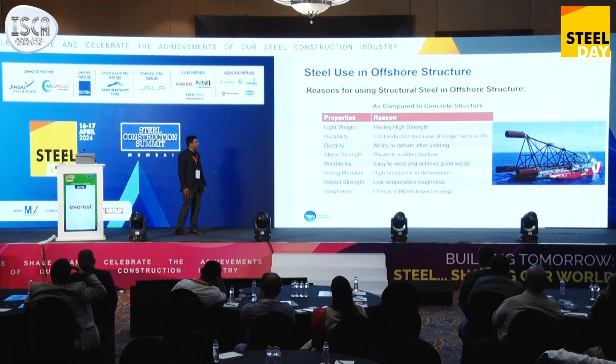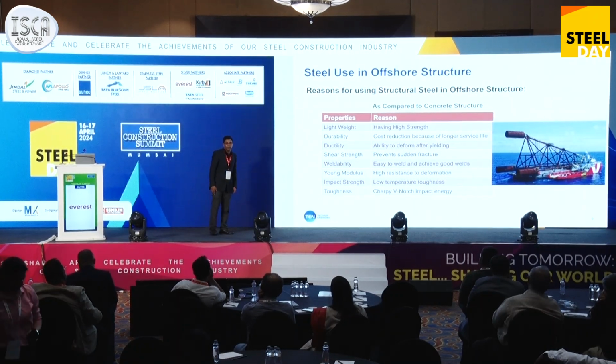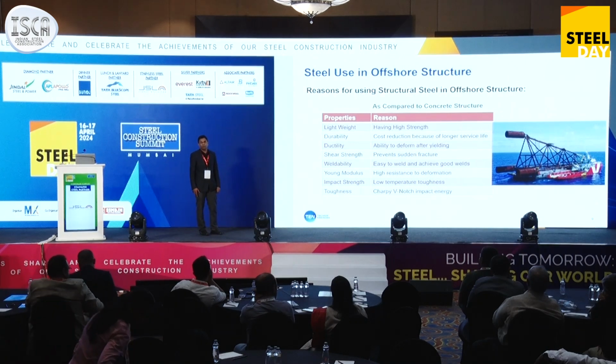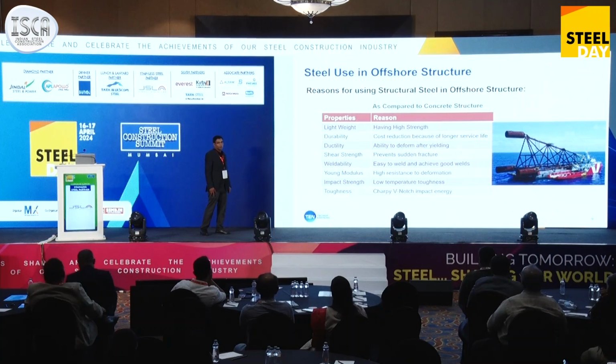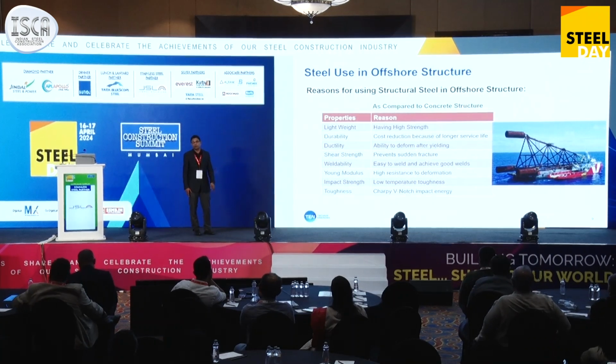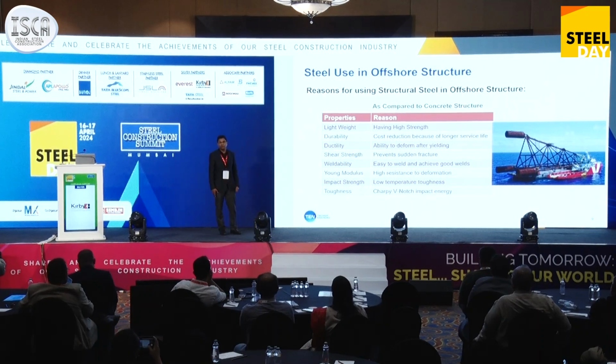One critical aspect I'll explain is durability. Your structure has to stand in offshore water for a long period, like 20 or 30 years, so there is a chance that your steel will corrode. For offshore, what we do is apply sacrificial anodes. We place those sacrificial anodes. In pictorial form, I can show you.